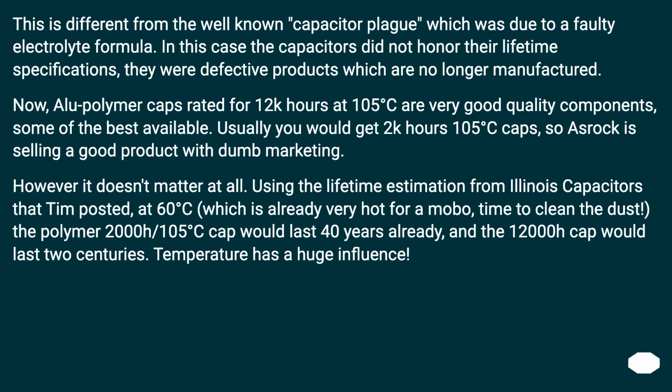However, it doesn't matter at all. Using the lifetime estimation from Illinois Capacitors that Tim posted, at 60 degrees Celsius, which is already very hot for a motherboard, time to clean the dust, the polymer 2000 hours/105 degrees Celsius cap would last 40 years already, and the 12,000 hours cap would last 2 centuries. Temperature has a huge influence.